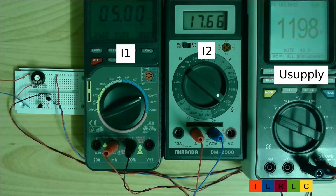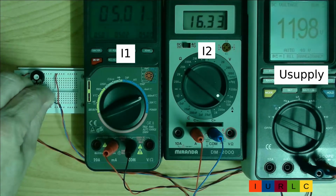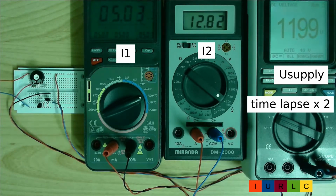I cool down the transistor T2, which is already hot, with my fingers, and we see that the current goes down. As soon as I remove my fingers from the transistor, it begins to warm up again and the current increases.